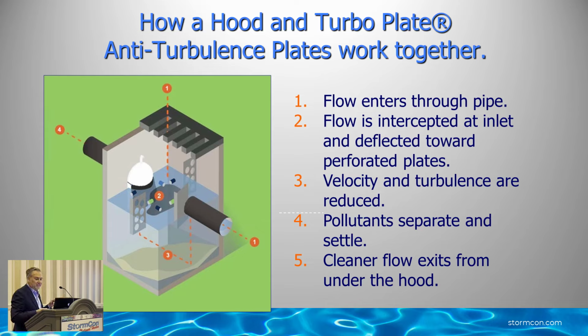So interesting stuff. But that's your basic concept with the inlet pipe, the solid plate, deflecting it to the side, and now that flow has to travel through all of those open areas in the perforated plates. Same amount of flow, increased area, velocity reduces, turbulence reduces, and things start to settle out better. I know I'm going to sound like a broken record, but there's only so much you can say about a philosophy that's this simple.